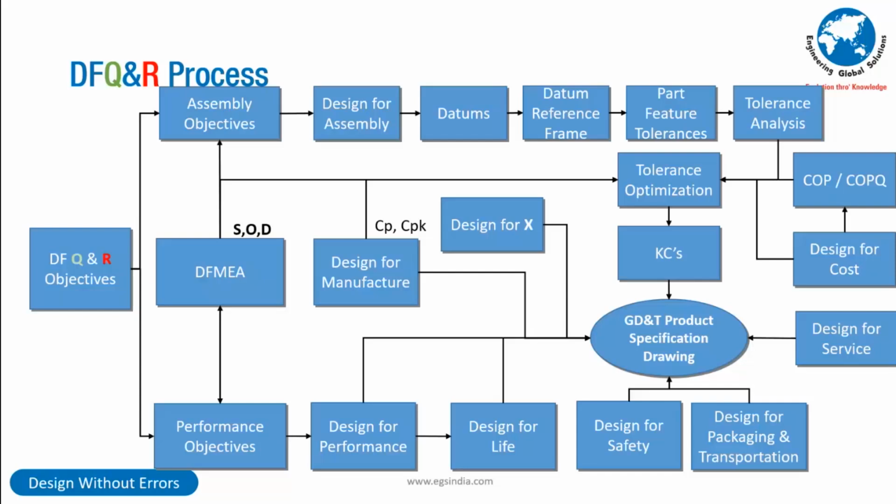See, I'm reminded of one instance in the past where one of our customers was developing a tool holder. And he was doing it in 2 dimensions using 2D software. And he had bought a very expensive balancing machine from Germany. And he was using it for dynamic balancing. We all know that static balancing you can do, dynamic balancing you can do up to second harmonics, and preventing the higher ones would cost you more money.